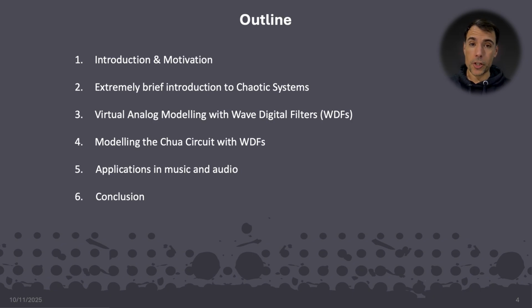So, following the motivation, I will provide brief introductions to chaotic systems, to virtual analog modeling with WDFs, and then we'll do a walkthrough of the modeling and implementation of the Chua circuit with WDFs, followed by a quick discussion about the applications of the wave digital Chua circuit as a chaotic signal engine for applications in music and audio, and finally we'll conclude.